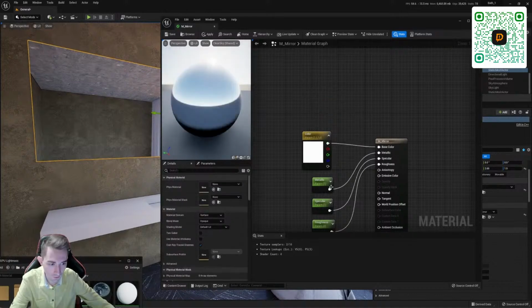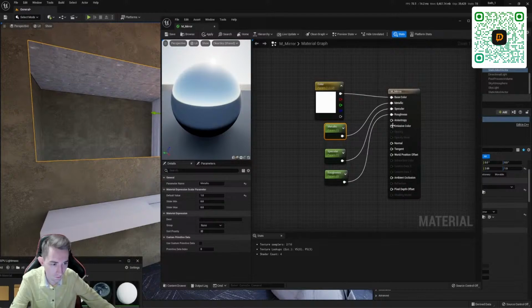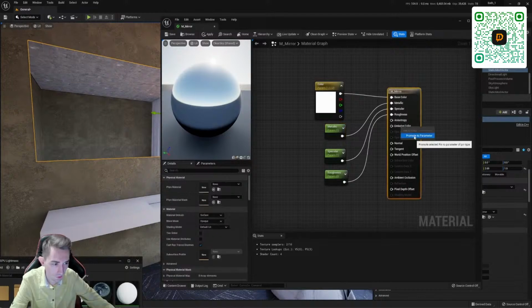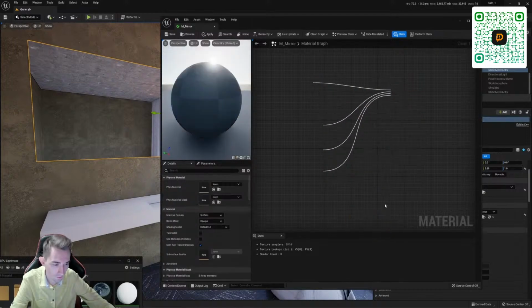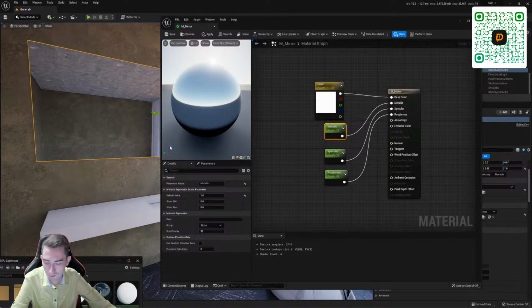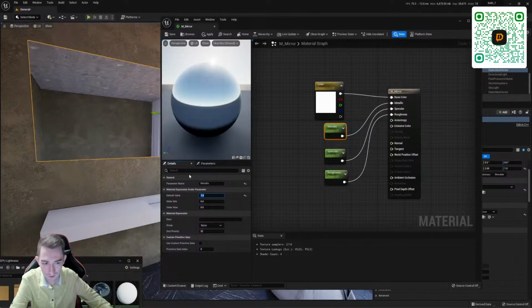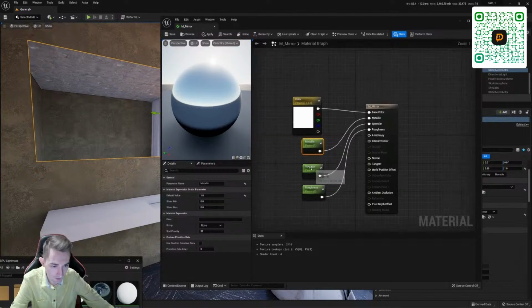Now I'm going to connect the color back. Then metallic. Such nodes are created easily. You can just right-click on the parameter. So that's it. We create metallic, because here the effect of metal goes. For Unreal, this is how it looks. If we put 0, then we will not get any mirror. With 0, there will be no metallicity. We put 1. Then specular.